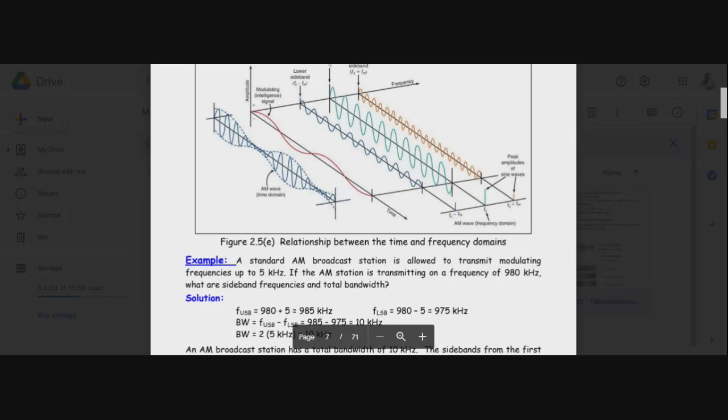we'll go on. I remember telling you about this diagram. All it's doing is summarizing for us what happens when you have amplitude modulation. The plot is really a plot in time. So the axis that goes at a slight angle from the back to the front of the screen is the time axis, and the one going from left to right, almost inside the screen, is the frequency axis. And so you'll find that the lower frequency is on the left.